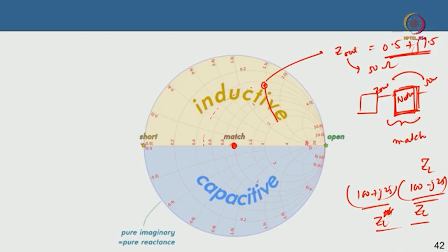So, what you have to do is take help of a parallel or series combination of inductor and capacitor, such that you can move on either the admittance circle or the impedance circle. Remember, whatever Smith chart you are looking at right now is in the context of Z, or impedance. However, in many cases it is useful to talk in terms of admittance, in which case the Smith chart can be flipped both as a mirror and upside down, and you get something called a Y Smith chart, or an admittance Smith chart. I will show you how an admittance Smith chart looks.